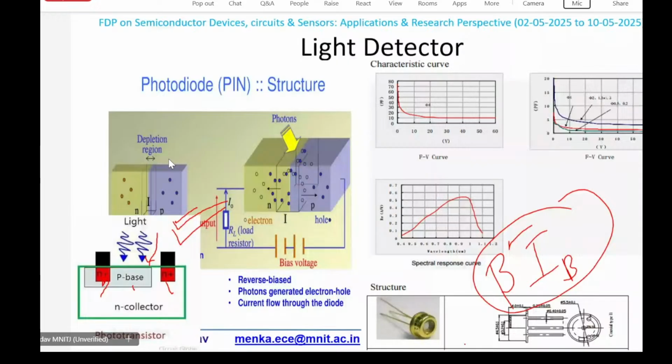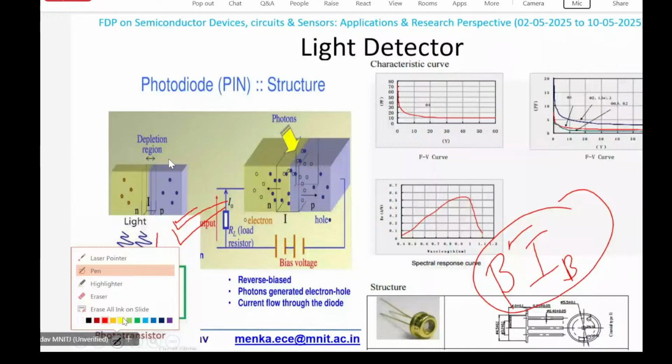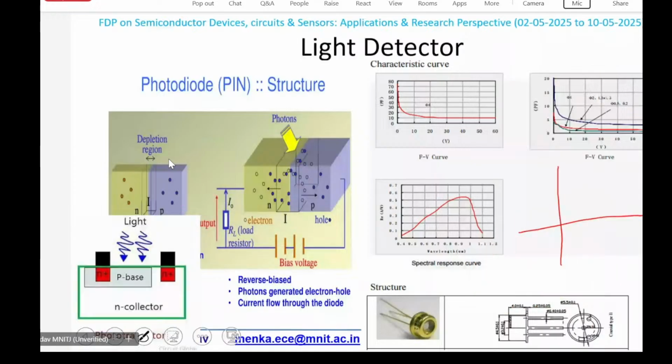In the forward bias, it was on after a particular threshold, right? And in the reverse bias, it was getting low. So this was on in the forward bias. In the reverse bias, if let's say I have taken this in milliamps, I am going to take it in nanoamps. Look at the scale, I have taken it in nanoamps. So this was your VD and this axis is your ID. In nanoamps, it is going to look in this way, right?